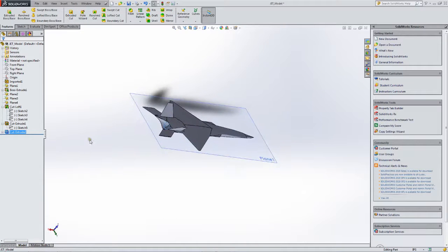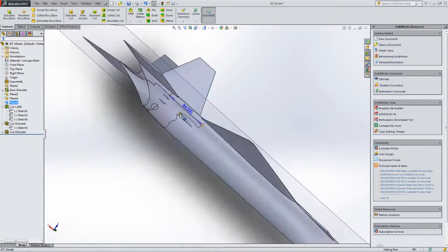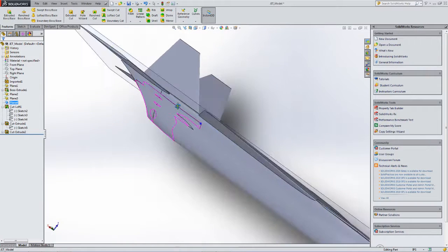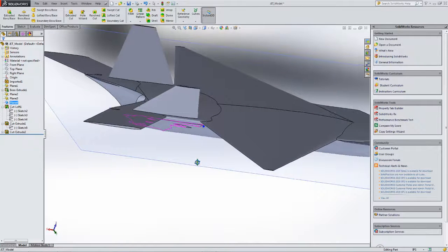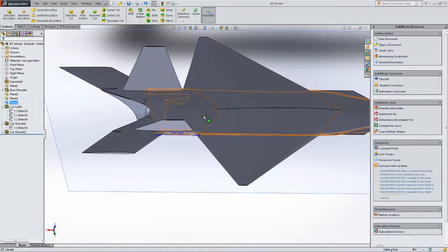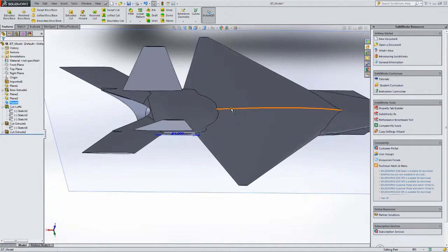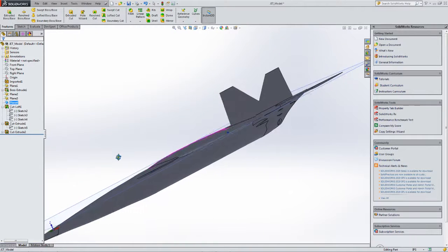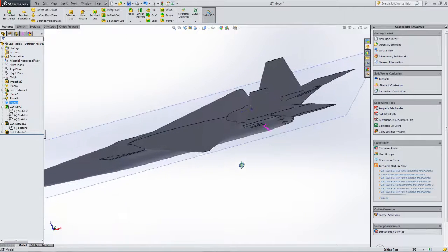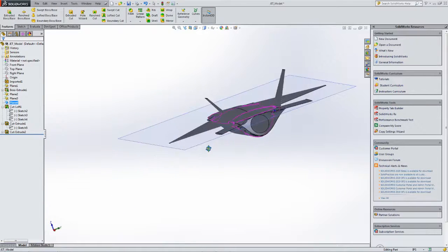I'm also going to use plane 4, which is further forward, and I'm going to do another extruded cut drafting outward, but not 17 degrees, just to make sure the sting doesn't. The rear of the force balance is somewhere here. Probably it's 4 inches long, and I don't want the sting to hit the model at all.